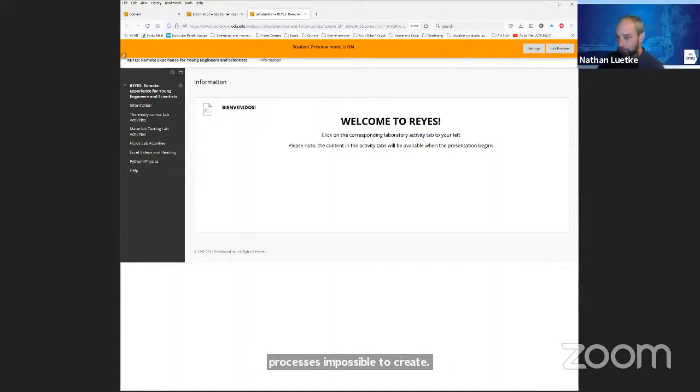A Carnot cycle is 4 internally reversible processes, impossible to create exactly, but we can try and get close to that. So, for example, a steam power plant, or a gas turbine you might use. The maximum theoretical efficiency, according to Carnot, is maybe 70, 80% usually. We might be running around 30 or 40% in real life. It's much lower than that.